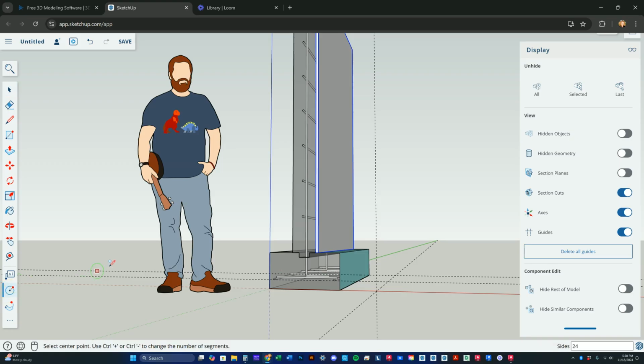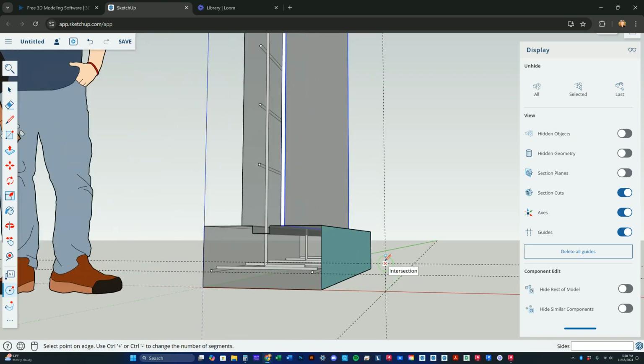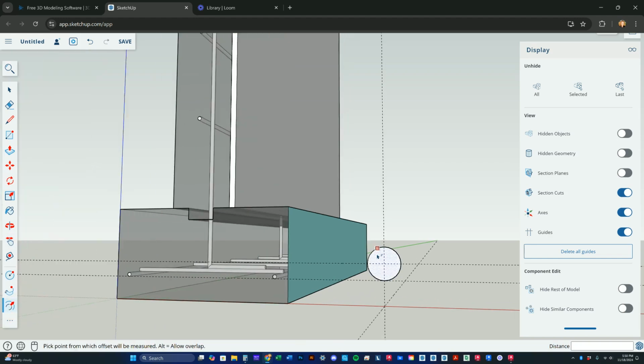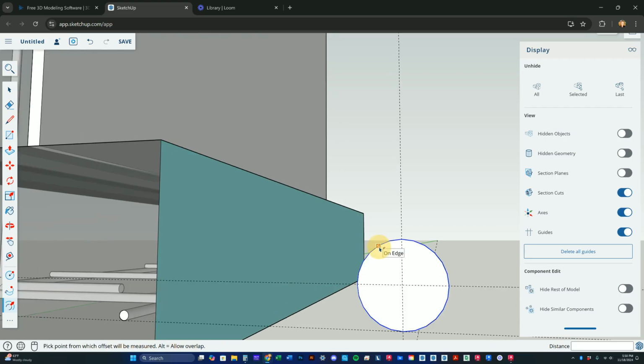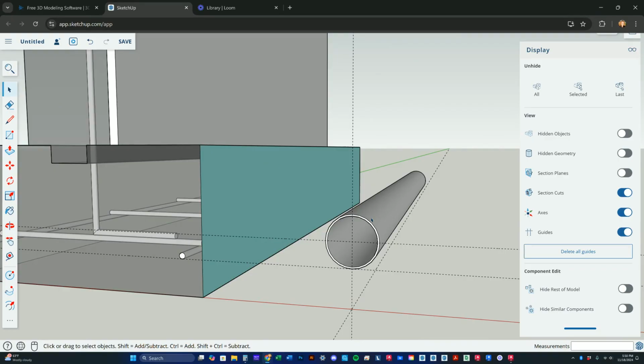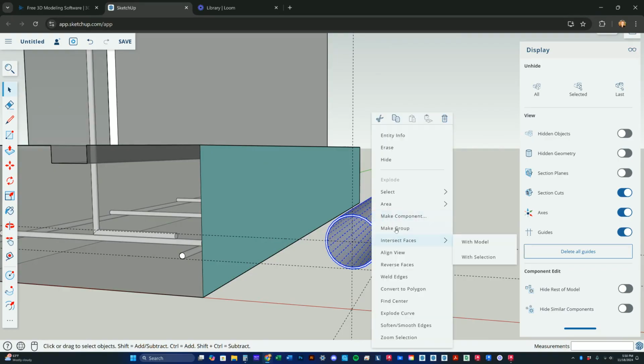And then we're going to pick our circle tool and we're going to grab that and come down to there. And then we need to make this hollow since we can. We're going to look for our offset tool and zoom in, and then we're going to pick this and pull in and type in 1/8 of an inch, and then pick the middle and then hit delete, and it will go away, and now you have a hollow pipe. Now pick your push-pull tool and you're going to push it all the way down. And then select tool, triple click, right click, and make it a group.